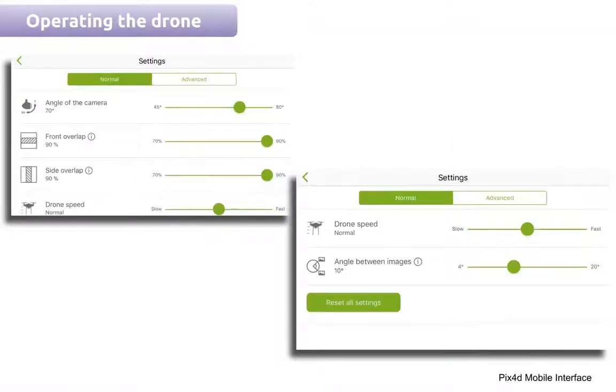So then another option that you need to select from is the amount of imagery overlap. And basically, the more overlap that you have, the more frequently the camera takes a picture. And so in the image on the top left, you'll see that the overlap is set to 90%. So 90% of the new image is also visible on the previous image. And on the circular mission, that overlap is controlled by how many images are taken based on the degrees of a circle.